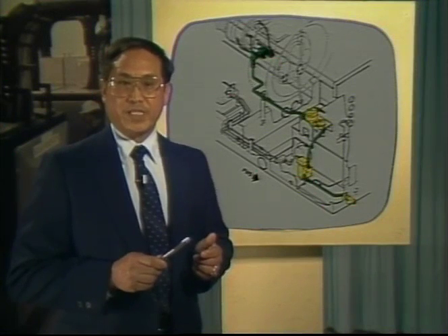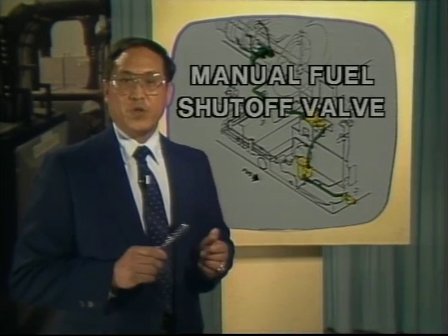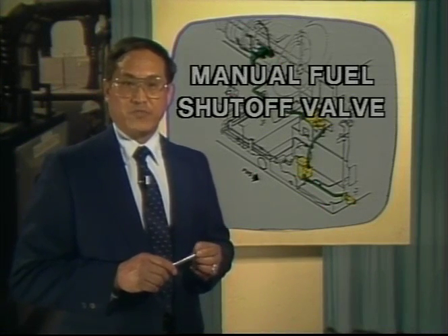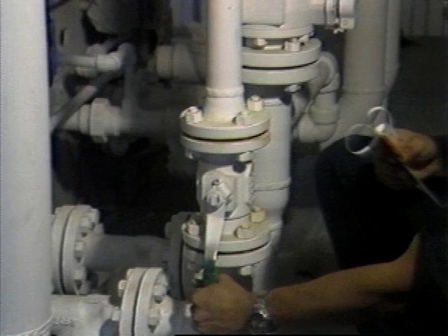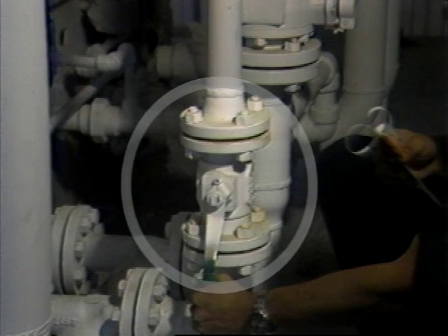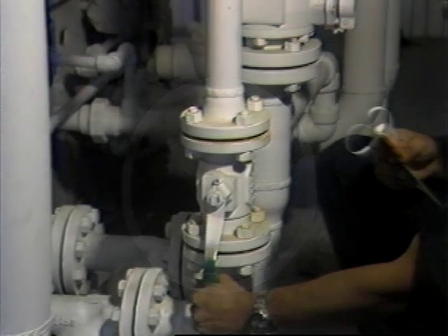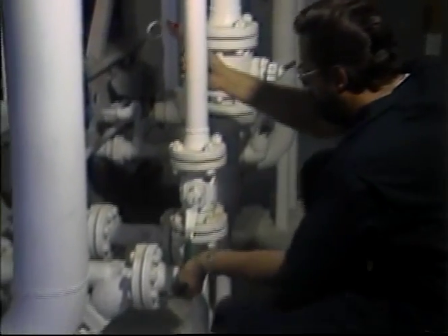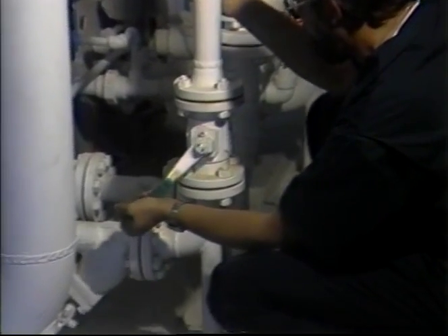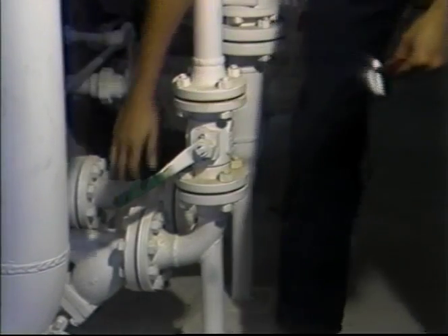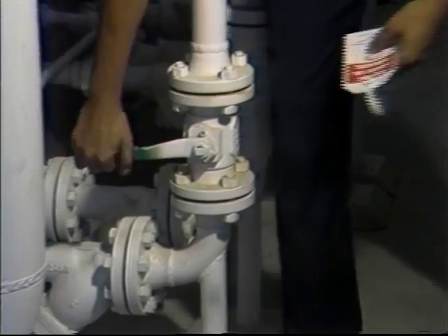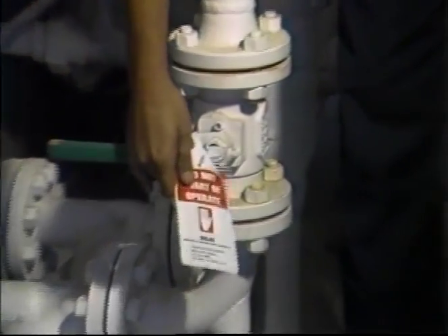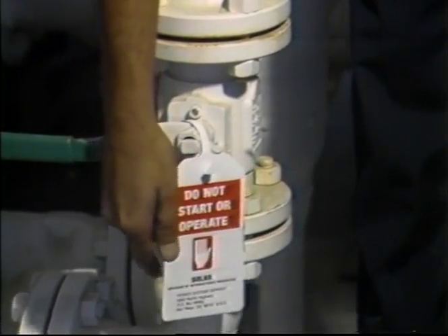Prior to entering the gas fuel system, fuel flows through a manual fuel shut-off valve. This customer furnished ball-type valve is manually opened prior to engine startup. In situations where no fuel pressure can be present, such as during maintenance or when the package is to be shut down for an extended period of time, the manual fuel shut-off valve must be closed.